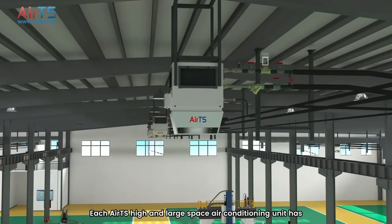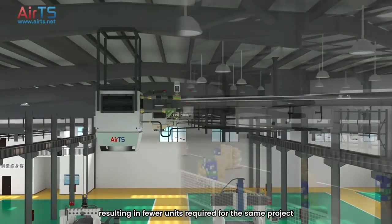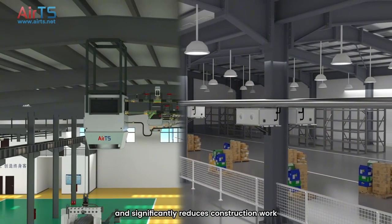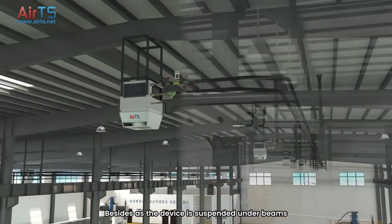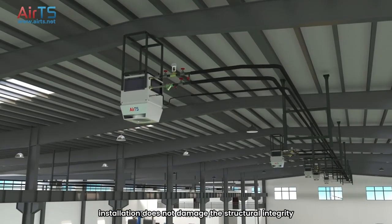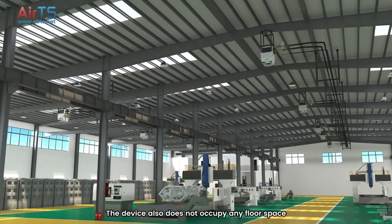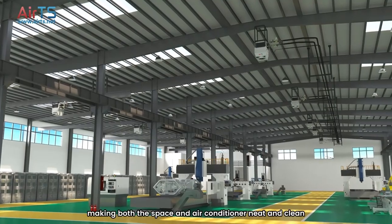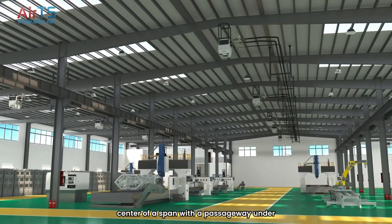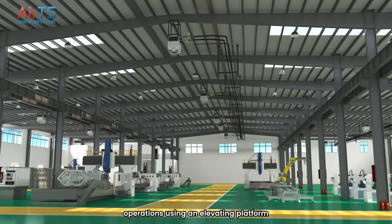Each AirTS high and large space air conditioning unit has larger airflow and cooling/heating capacity, resulting in fewer units required for the same project. This simplifies the system and significantly reduces construction work. Besides, as the device is suspended under beams without requiring additional secondary beams, installation does not damage the structural integrity due to the use of finished steel hangers. The device also does not occupy any floor space, making both the space and air conditioner neat and clean. The equipment is suspended in the exact center of a span, with a passageway under, facilitating maintenance and servicing operations using an elevating platform.